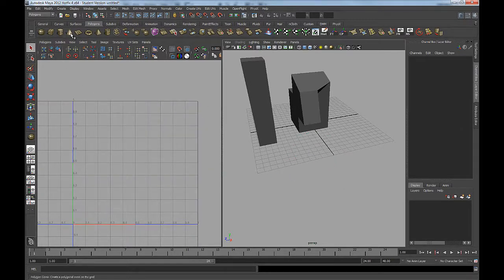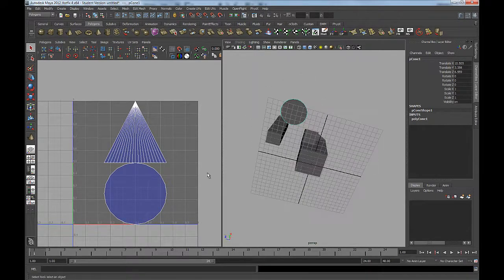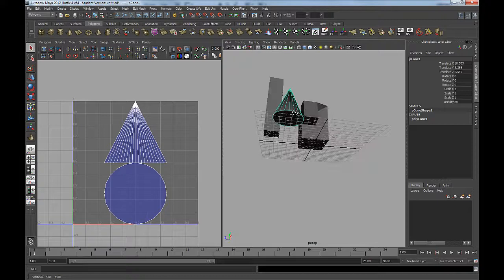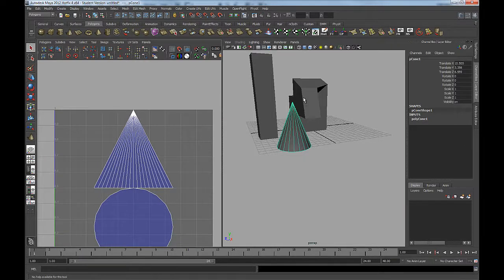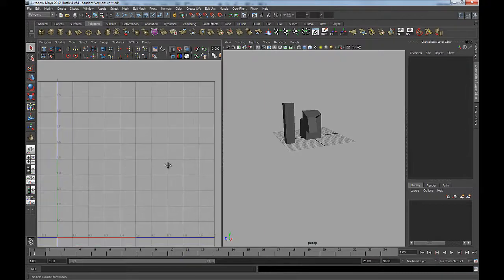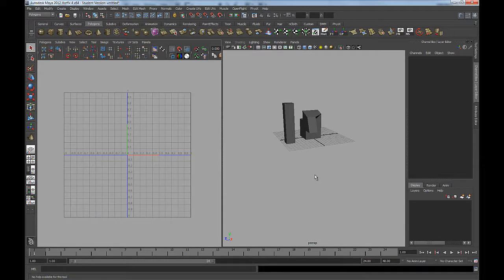Okay, the cone, let's have a look at this. So with the cone, you essentially get that shape. Once again, that's actually not technically correct compared to this object. The circle at the bottom is basically what you see on the object, but these triangles are not actually shaped like this. Technically, to get this shape flattened out, you would have to make more of a fan shape, so it would be kind of triangular with a rounded bottom. So you can see there are some issues with these default templates, which is why you don't use the default templates. You actually edit them and customize them for your object.